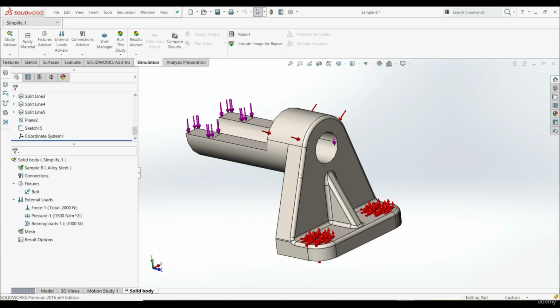But as well, we have to be careful what kind of mesh we create. We have to be careful that our elements are well shaped, because the shape of the element affects the final results: stresses, displacement, and strain. And if we have a distorted element, then our results will be inaccurate. As well, the number of elements plays a role. If we have a lot of elements, that takes a lot of time and a lot of memory. So we have to balance the number of elements with the shape of the elements.